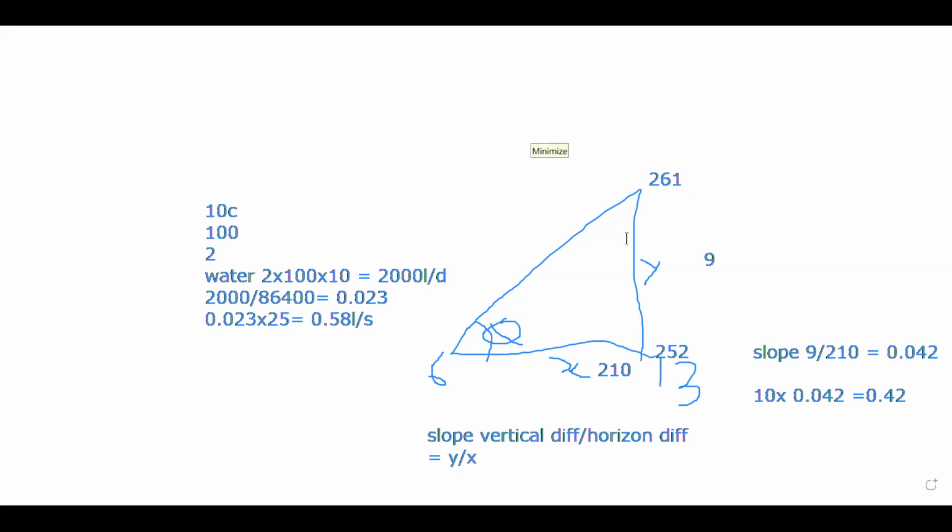Sir, is it possible to get a negative value of slope? Yes. It means you are losing pressure somehow. It means there will be losses there. Water can flow in both directions. You can have a negative slope, but it means it's working against your pressure. In water reticulation, you have this pressure that you want to maximize, so the more negative slope you have, the more you're losing.